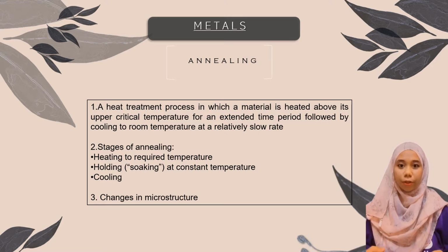The second treatment is annealing. Annealing is a heat treatment in which material is heated above its upper critical temperature for an extended time period, followed by cooling to room temperature at a relatively slow rate.